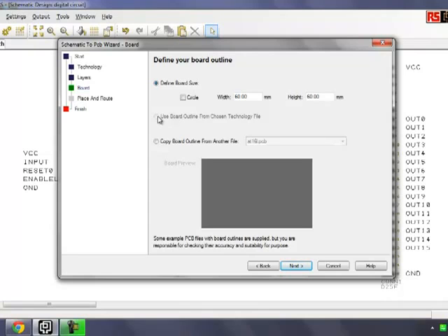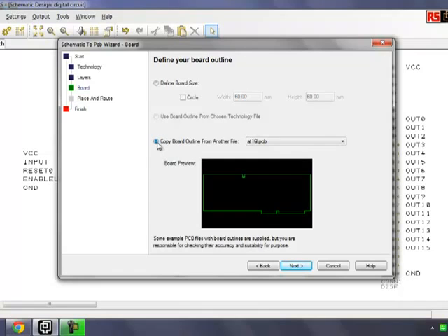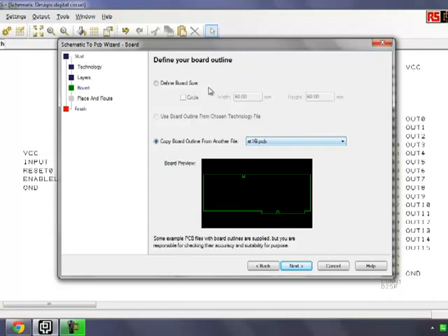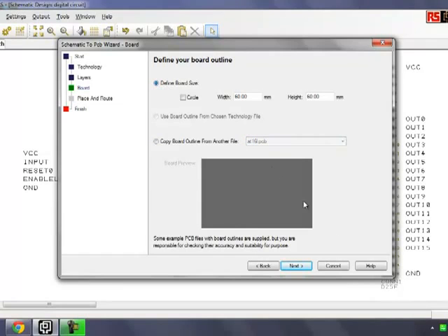Maybe you need a particular cutout or a mitre, an angle of some description. You can design these, save these, and bring these into the PCB editor yourself. This is in a different lesson though. Also, there are a number of boards within DesignSpark PCB, preloaded for Euro cards, that you can use. Well, for today, we're going to go with the standard 60mm square PCB.